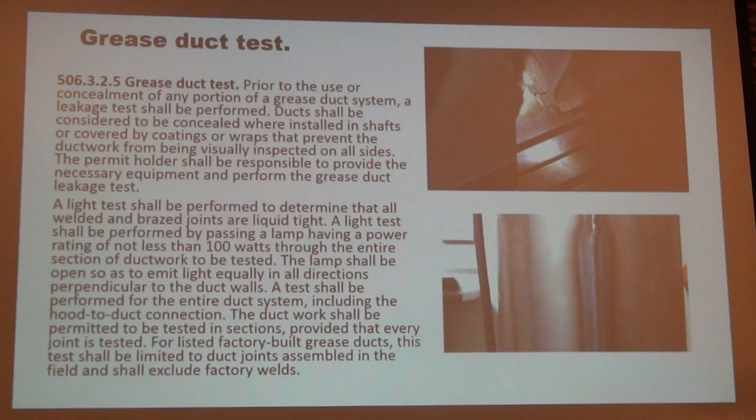Right. So there's alternatives if you want to require a pressure test. Well, they want it to hold that way. I don't have a problem with that as far as that goes. Hey, Mark, if you did a pressure test, what kind of pressure would you use? I would use a very low pressure. Yeah, you don't want to use anything too heavy. And you want to have something like a magnehelic gauge or a water column gauge.